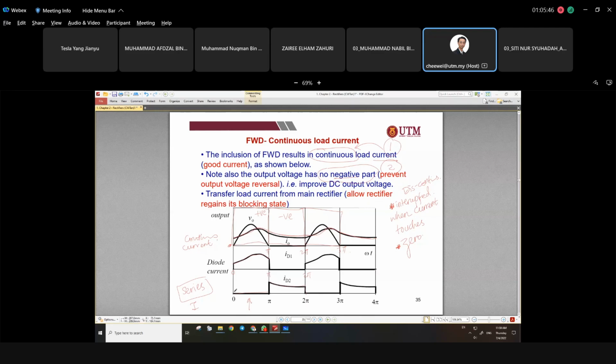If you draw the dotted line, you see it's actually the same as I out. So that is the I out reference. Okay, we just split it into chunks: the positive half cycle for D1, and the negative half cycle for D2, individually. If we combine ID1 and ID2, we get the I out.